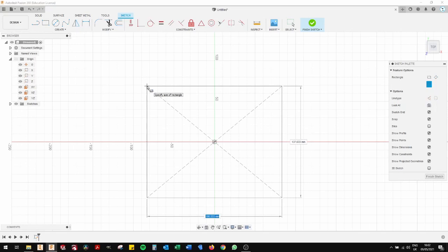For me, this is important because when you make a spoilboard, you are working from the center instead of from the bottom left as your origin point. When the spoilboard's down, most of your jobs will probably be orientated from the bottom left, but for a first job, you're starting in the center.